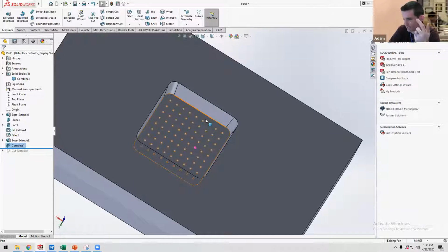If you were actually doing this for injection molding, this mold would be 3D printed, in which case the negative cavities are not as easy to print as some positive shapes. So resin would definitely get stuck in these holes and would not resolve if you were doing that.